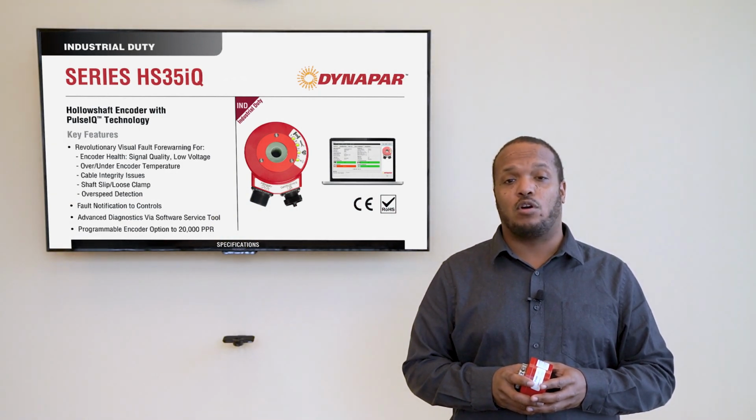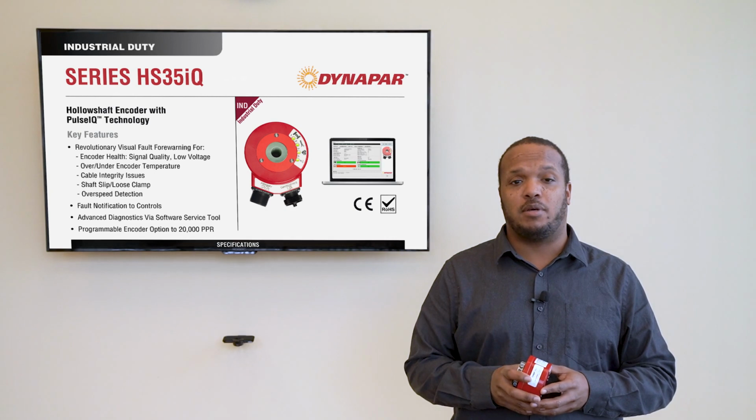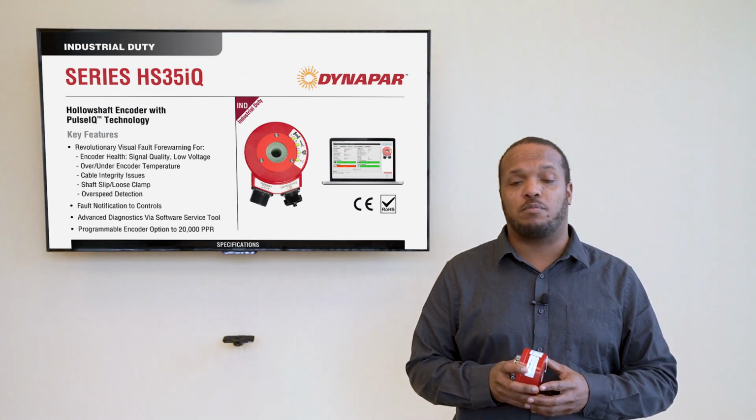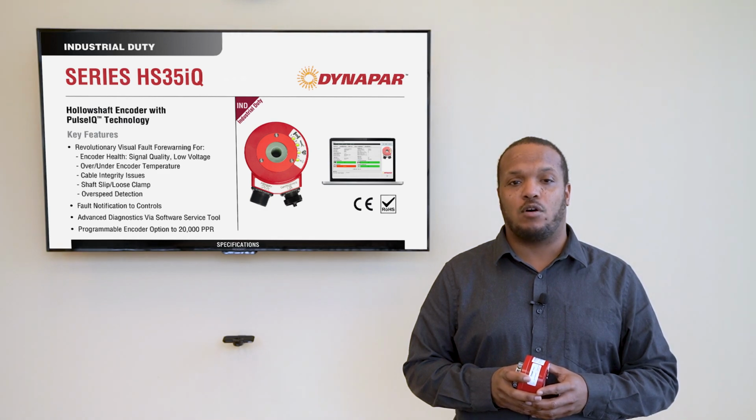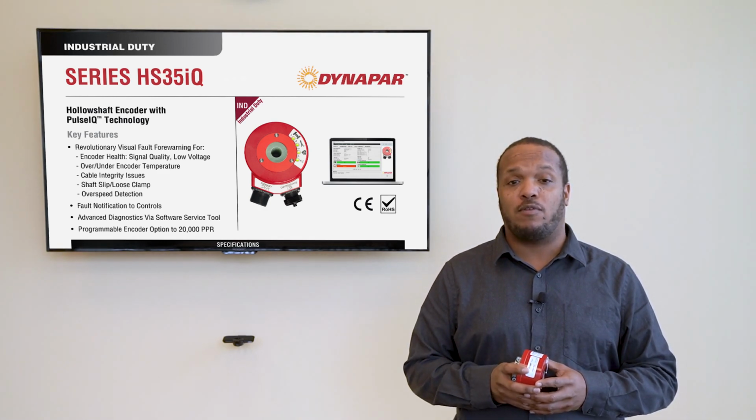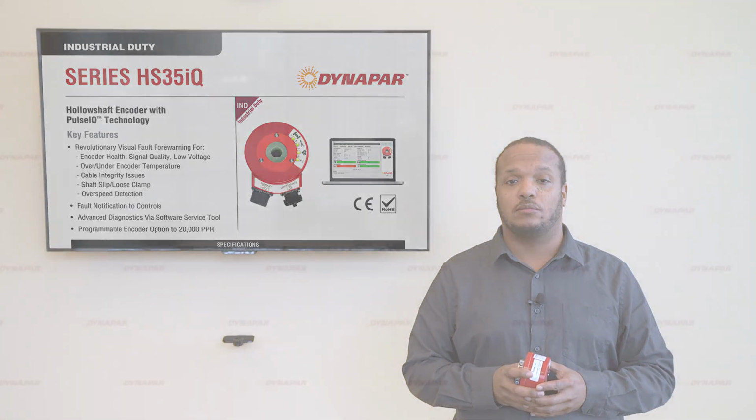In today's video, we're going to overview the cable fault monitoring capabilities of the HS35iQ encoder with PulseIQ technology. Whether you have the programmable or the standard version of the encoder, both will allow you to monitor cable faults such as opens and shorts.